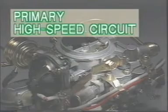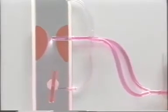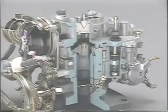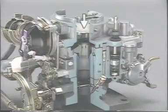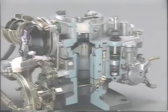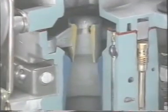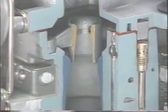Next is the primary high-speed circuit. The construction of this is similar to that in the carburetor model we looked at earlier. It is the most widely used main circuit, although there are other mechanisms which activate to assist when extra power or speed is needed. This side is the primary barrel on this model. The venturi is designed this way for maximum mixing of air and fuel.